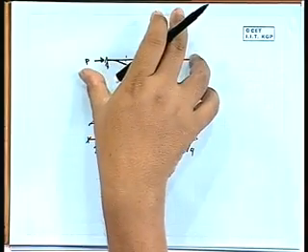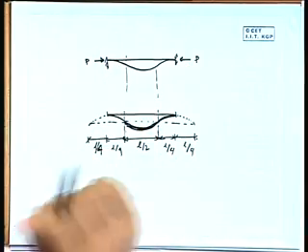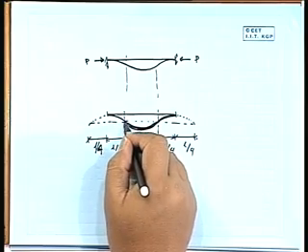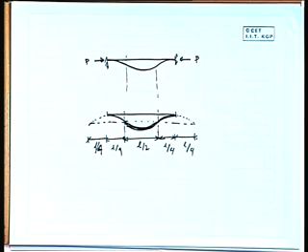And really if you solve that problem with our differential equation EI d2y dx square equal to the moment equation, you will find here at L by 4 you will get the curvature equal to 0.